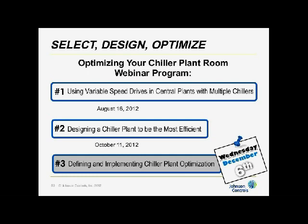I assume you're talking about the range across the tower? I wouldn't say there's necessarily that so much as you may be really talking more about the approach. What is the best approach? If I start with a 78-degree wet bulb and I have an 85-degree condenser water, that's a 7-degree approach. What's the best approach? Well, that sort of depends upon the energy of the chiller versus how much you can slow the fan down on the tower.